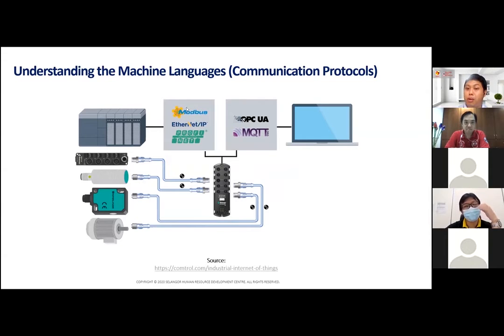The most common one will be Modbus. Profinet will be more Siemens-centric. Ethernet IP are also available. So these are communication strategies to the control level sensors. Now, if you want to talk to your systems in ERP or even in MES, some of the common protocols are like MQTT, right? OPC UA, or even what we call REST API, right?